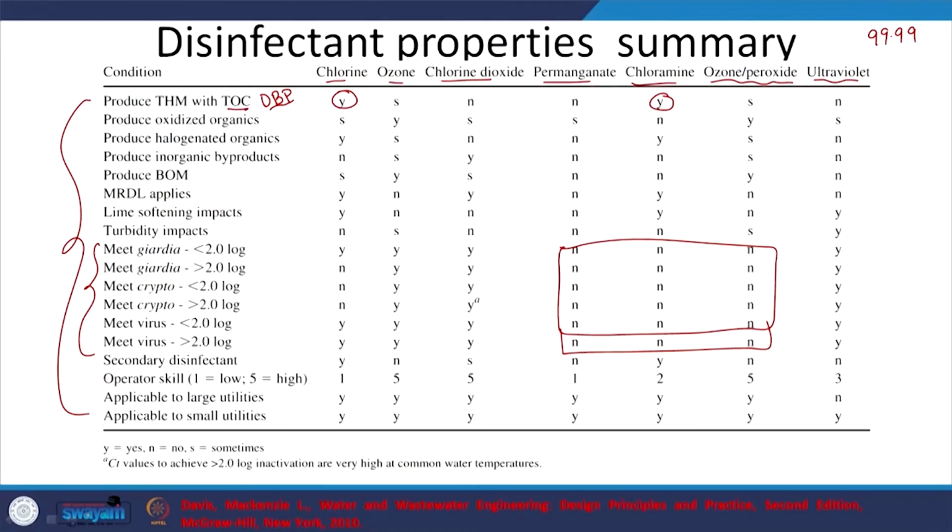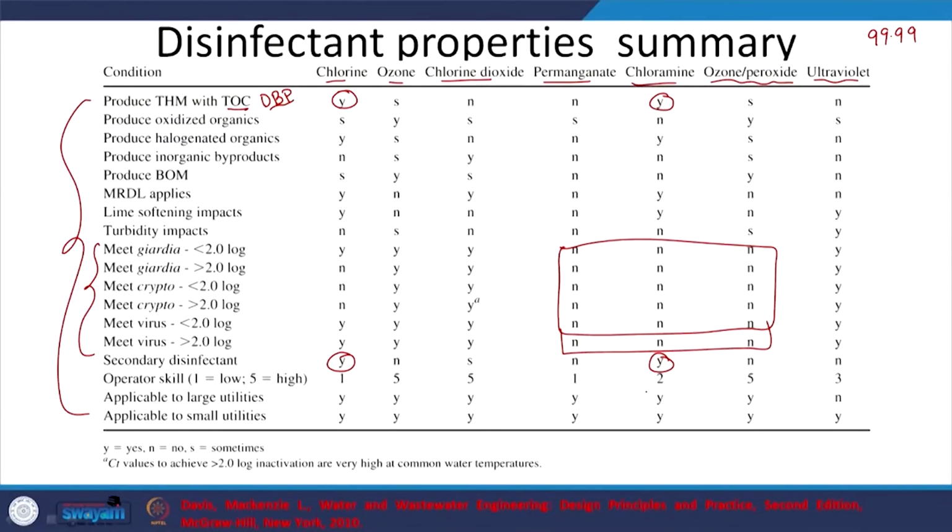So, secondary disinfectant, as in, I am assuming that it is about the relevant residual disinfecting properties. So, chlorine, yes. Ozone and UV, certainly not. Chloramine, yes, right. So, obviously if I want to have a residual oxidizing capability in my water, I need to choose chlorine or chloramines.